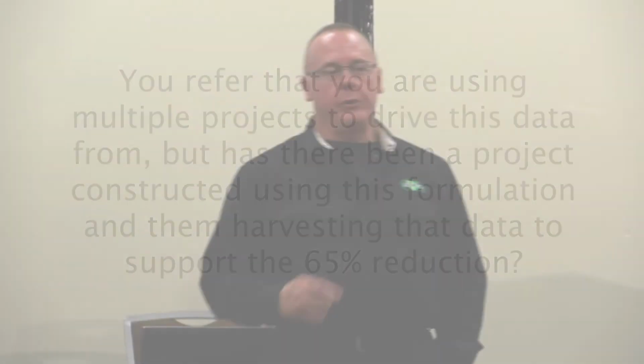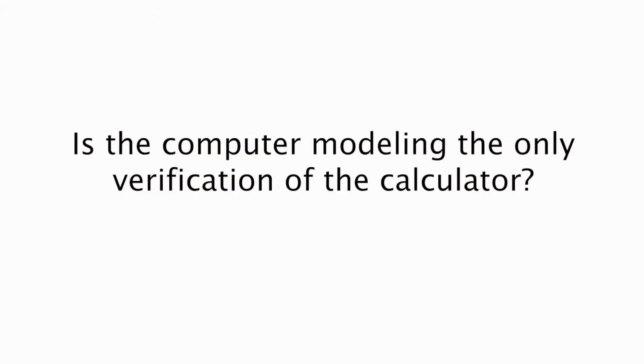We don't have actual field data. We have anecdotal data. In other words, we've looked at other studies that people have done and what the actual demand was. There's an ASHRAE study that I looked at. The UK just published a study that they did on residential apartments, and I looked at what their measured actual demand flow was. We put the same number of plumbing fixtures in our calculator, and we were almost spot on with the actual measured peak flows.